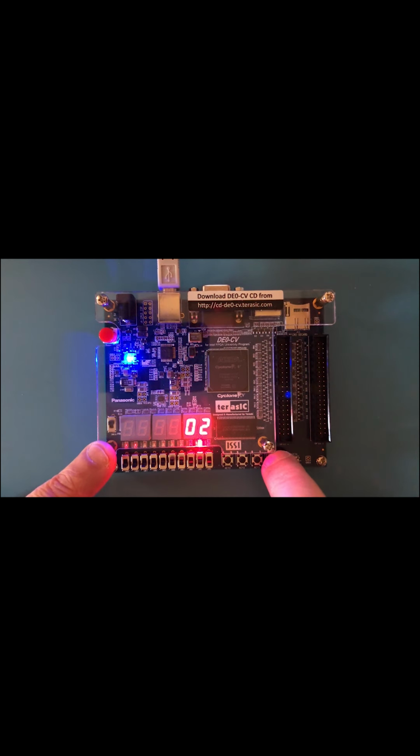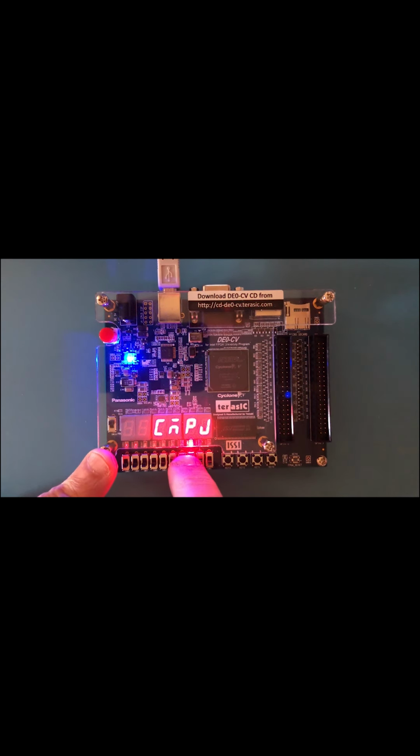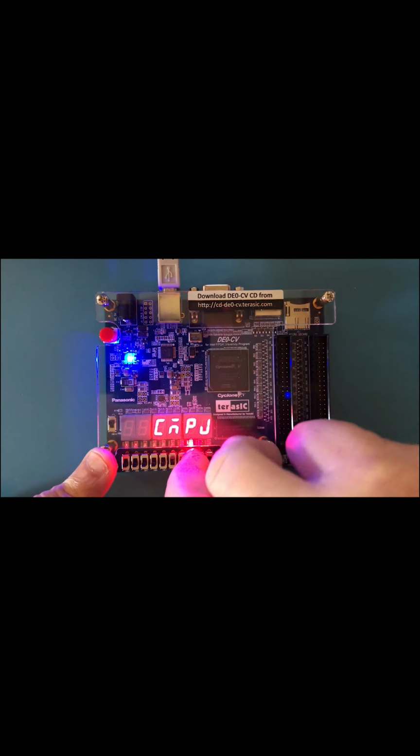The difference is that in the third one we might see a different result. So this is LDI. Let's switch to what's in the ALU. It's 0A, which is 10. Now go back to instruction 3, instruction 4. I know that instruction 4 is different, so let's see what's in instruction 4. It's a compare jump. The program is going to compare two values, and if the first value is greater than the second, it makes a jump, or not. If not, it just continues, which in this case I know it's going to do.